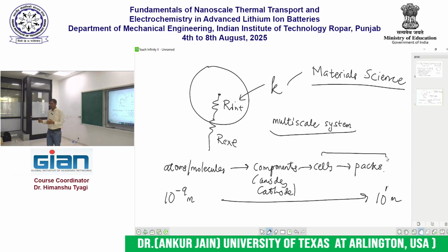He says they move their battery packs using forklifts. You know what a forklift is, right? Suppose the forklift operator is negligent and he or she runs the forklift into a bunch of battery packs, and they fall down on the ground. The very act of the battery falling down on the ground may rupture it and cause a thermal runaway event. So you can imagine there are all kinds of practical problems that storage and use of battery packs can cause. Can you come up with some interesting question that you want to answer in that regime?